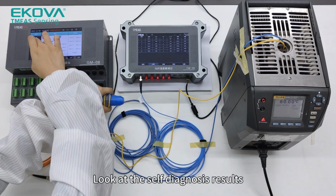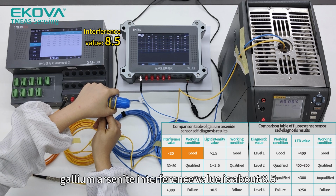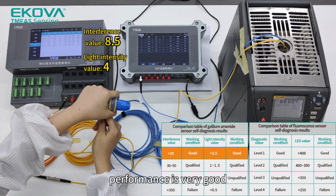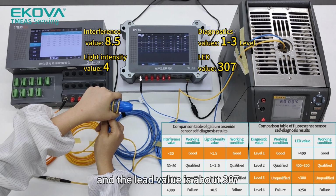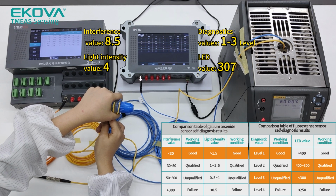Look at the self-diagnosis results. The gallium arsenide interference value is about 8.5. Light intensity is about 4, indicating that the temperature measurement performance is very good. The fluorescence diagnostic value jumps between grades 1 and 3, and the LED value is about 307, indicating that the temperature measurement is not qualified, is at a critical point, and the performance has been affected.